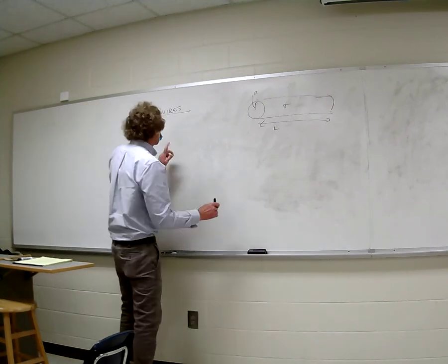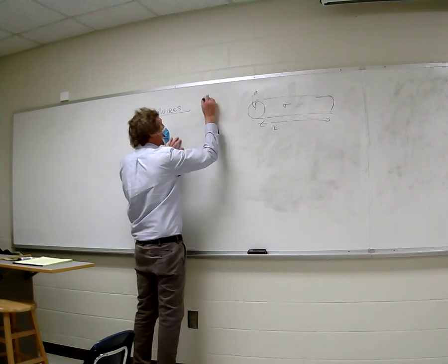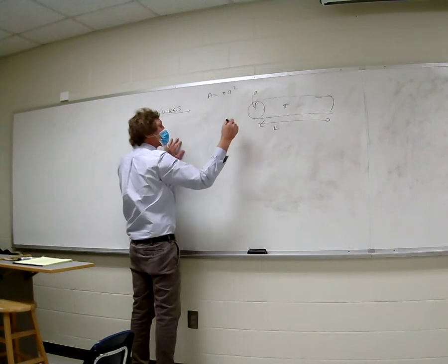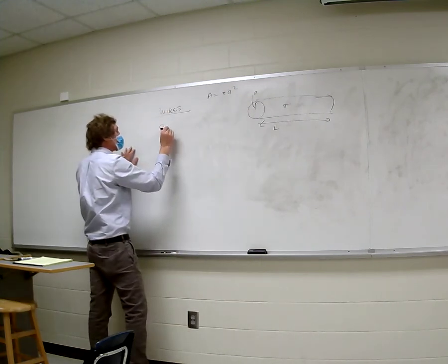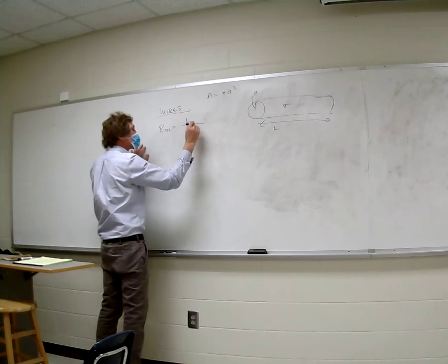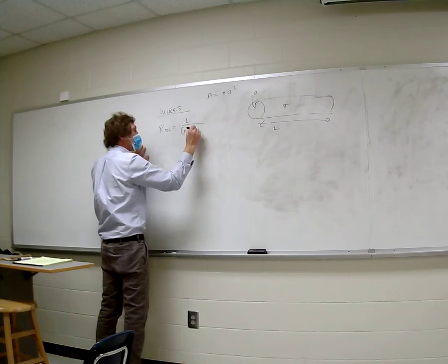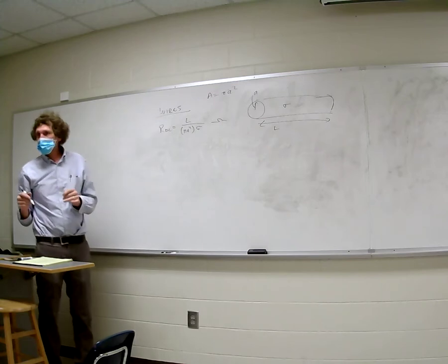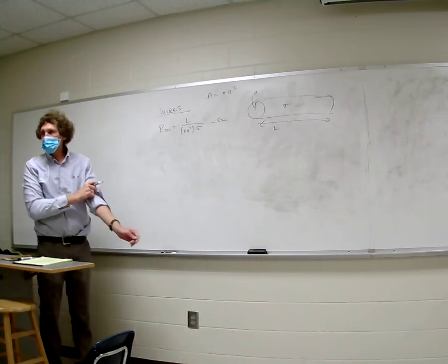All right, so when we have this there, the first thing we look at, well, let me put down the area. Here is pi a squared, and therefore the DC resistance of wires is proportional to the length, inversely proportional to the area, and inversely proportional to sigma. And I think we covered that on Friday. That's something you should know pretty well because you've seen this before, right?